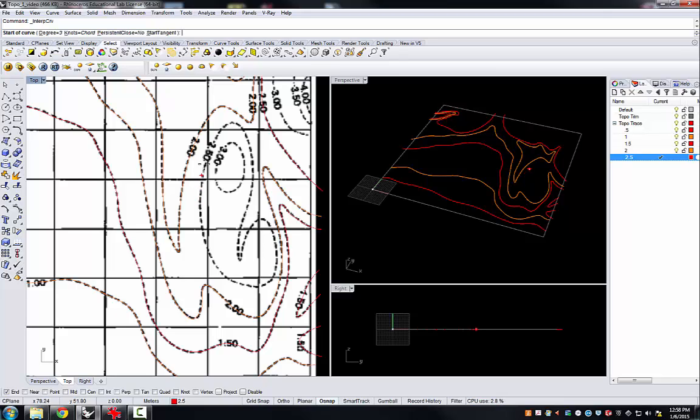In this case, you want to start somewhere on this curve, and it's important not to start in the tightest point in here, because this curve wants to smooth itself from point to point. It's best to start on one of the flatter parts of the curve, say here, and then proceed as we've been doing, putting more control points in the tighter areas of curvature and fewer in the smoother areas.